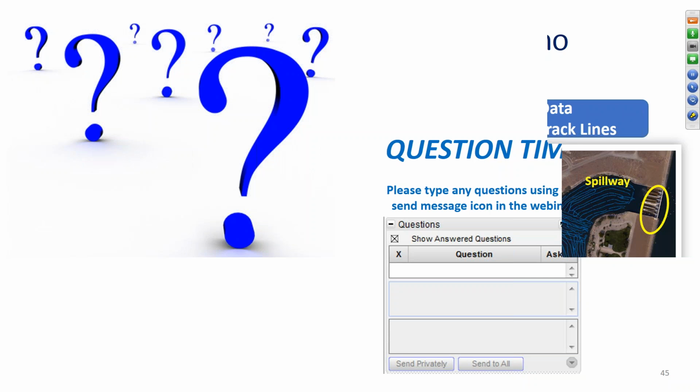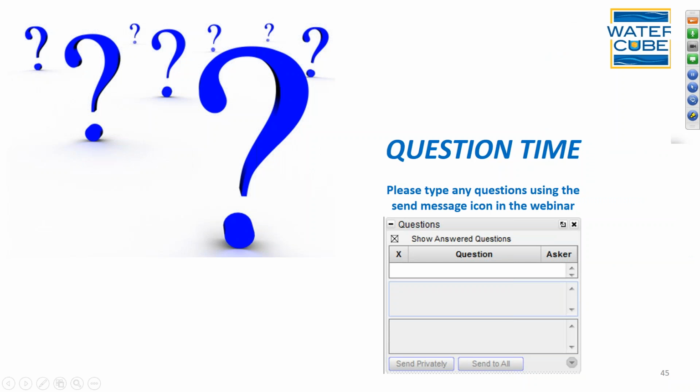Yeah, and just one comment to add to that. In terms of data screening, for example, back to the Silver River, quite frequently when the ADCPs are tracking, they do track quite well over the submerged vegetation because it's so dense. So in that case, we're not providing the true bathymetry of the river reach, but more or less the flow depth along that reach.